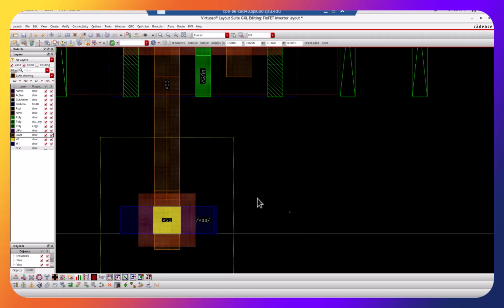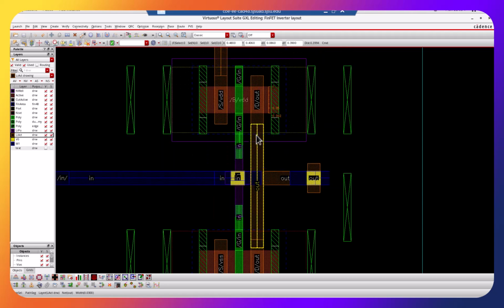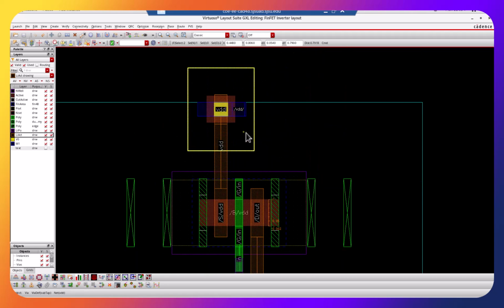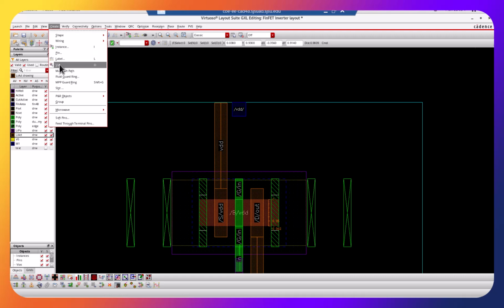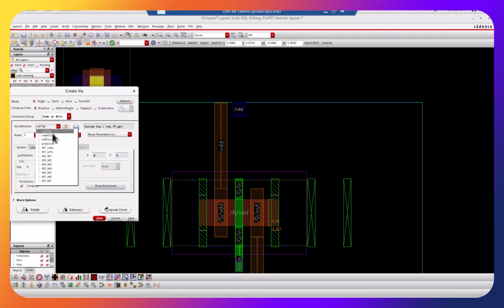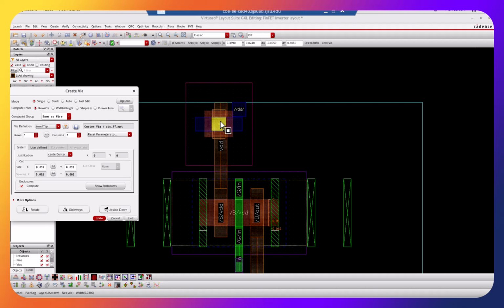Okay, I have the P sub here. So maybe on the top, I made a mistake. I thought I did N-well, but so I click on it and then press the delete key, right? So I need to do it again, create via, yes, thank you. And then we will do N-well, okay? Yeah, N-well is the right one because you will see the N-well.